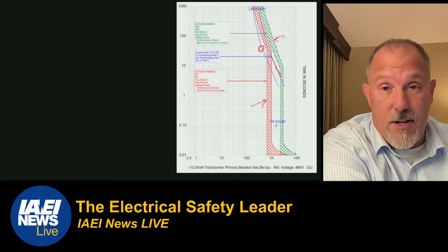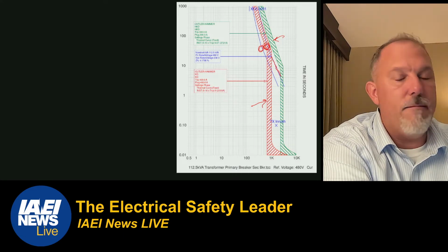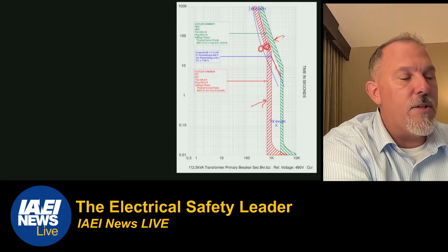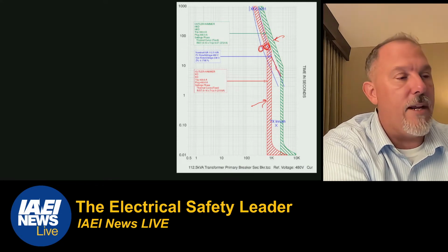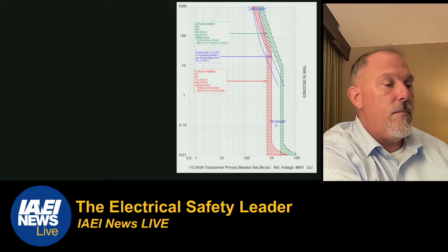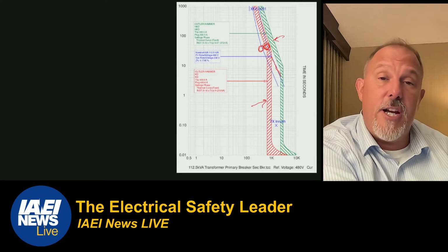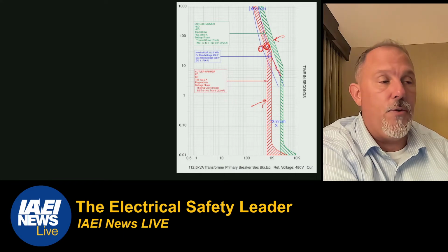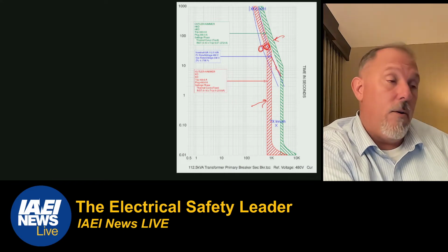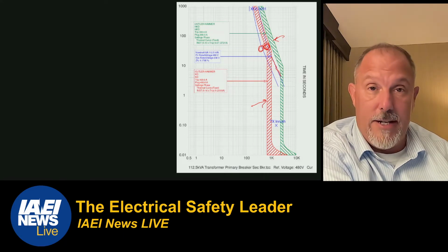I get adequate overload protection for this transformer because I'm in this region here, but I feel comfortable, very low exposure, and that device is going to trip in enough time that you're not going to damage the transformer. But that's by the code. I mean, even if I didn't like that, I could not reject it based upon the National Electrical Code. I could say, I don't feel you're protecting the transformer well enough. Okay, well, that's your opinion. It's not a code-related issue.